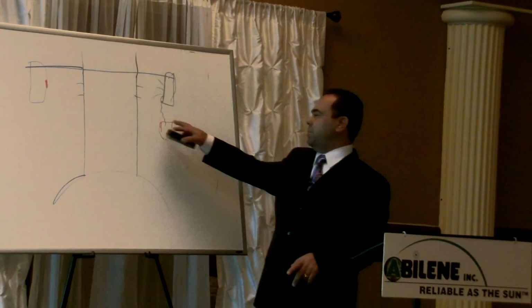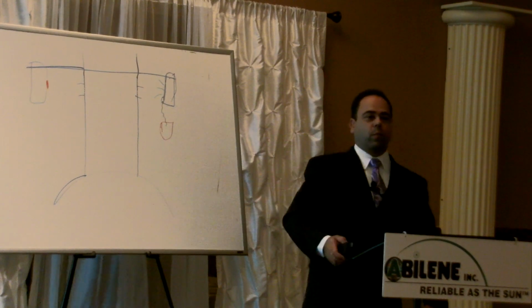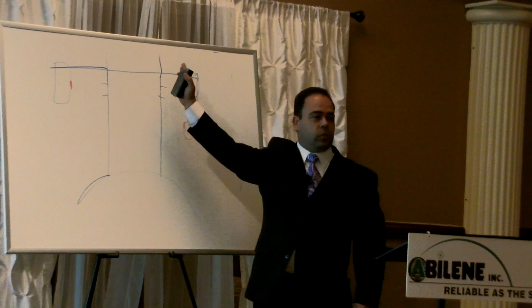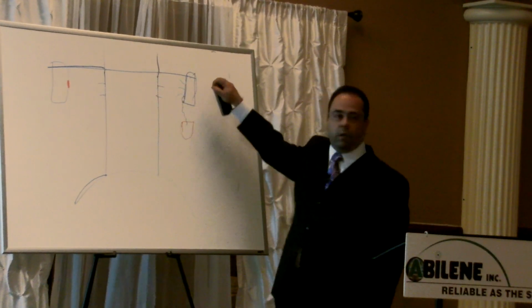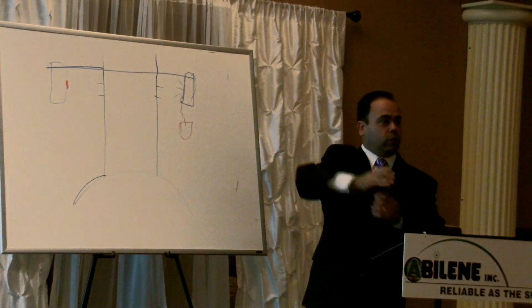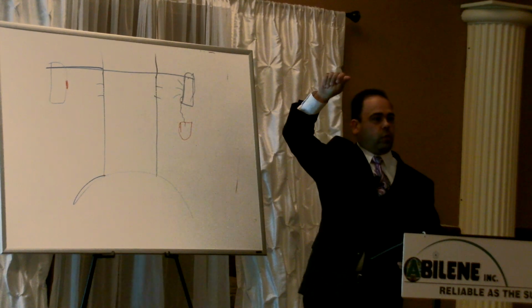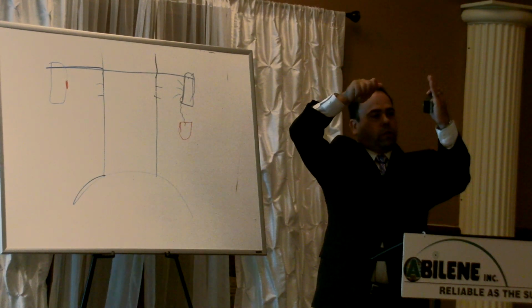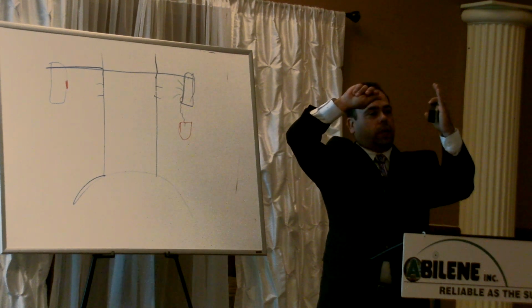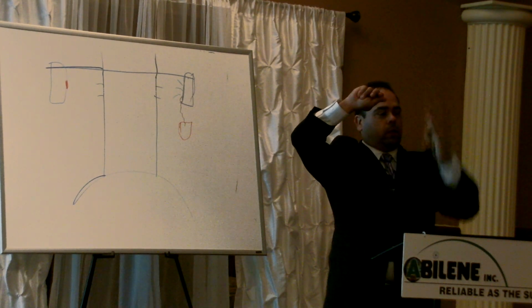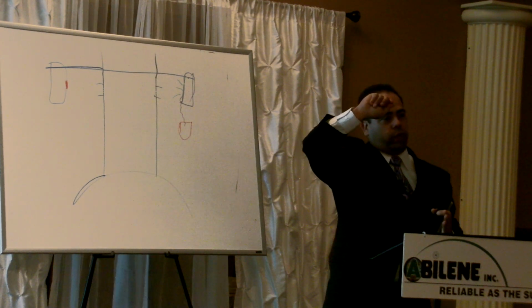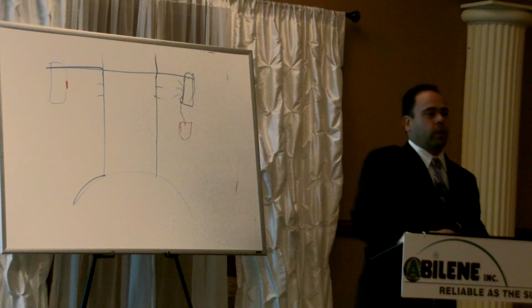So on the smoke alarms, when we go in, take the paper off. Try it next time. Put it in front. See what it does. Lower down the intensity, you know, the little dial on the back of it. It's for all you electricians, all right? Just put the lens in front of it, lower the intensity of the light, wait for it to ring, drop the lens, see if it shuts off. Then just raise it up a quarter of a turn, okay? Make it a little bit brighter.